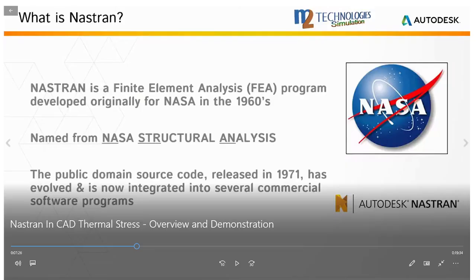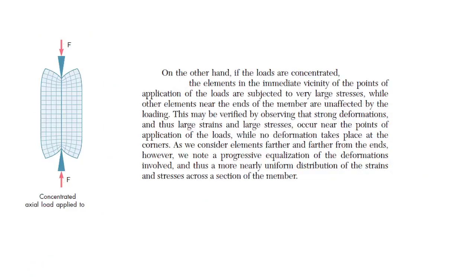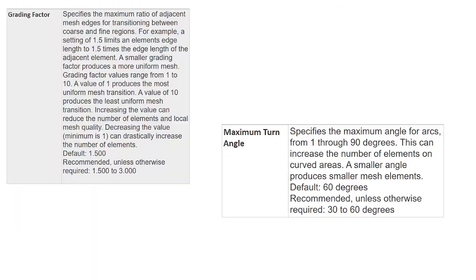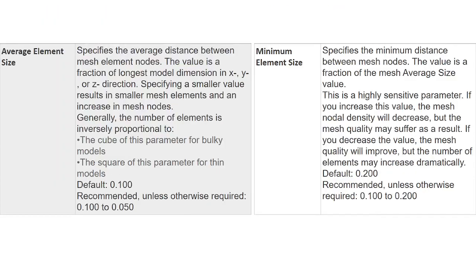First, why not, first talk about the local mesh control technique: in the vicinity of the discontinuities, also abrupt changes, since there will be greater stress values, stress concentrations, at such places we need to solve the problem more accurately.